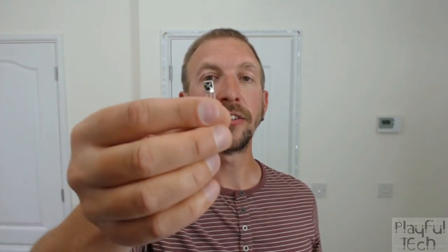Now in your television or other device that you control with an infrared remote, you'll get a component that looks like this. This is an infrared receiver module, and it's able to detect the light given off by an infrared LED and to also translate that flickering into a discrete sequence of on and off values. So I've got one of these receiver modules here wired to an Arduino, and the Arduino is running a sketch that's just going to visualize the raw output that the receiver captures when I point my infrared remote control at it.